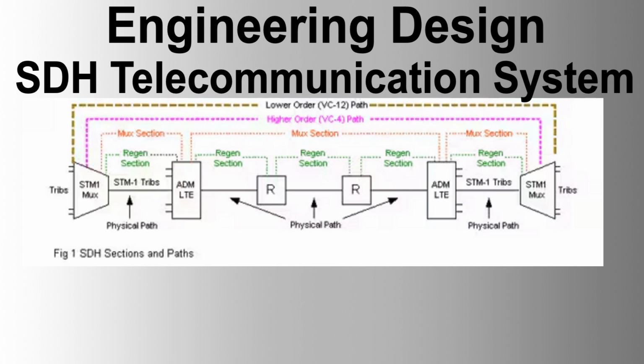Control center integration. The NMS shall be tied into RTUs through volt-free contacts for monitoring SDH status and alarms, allowing overall system status to be monitored by the process control operator.